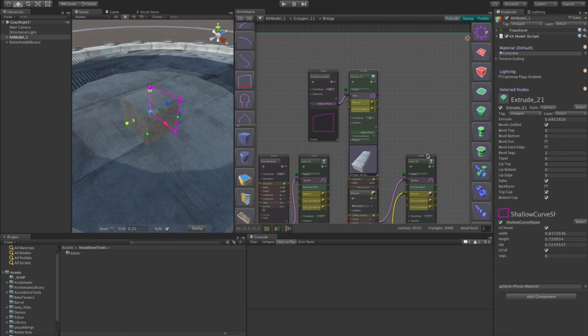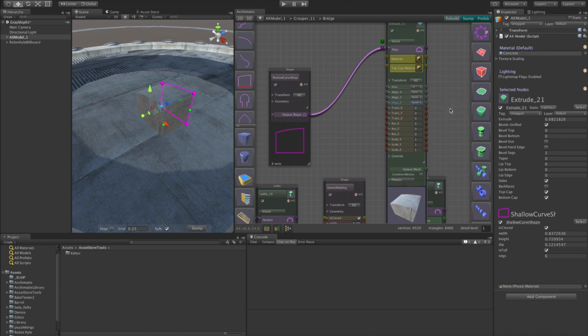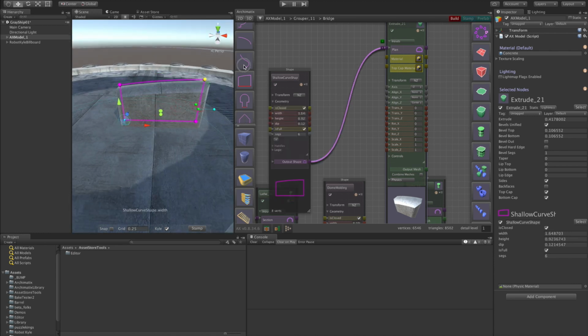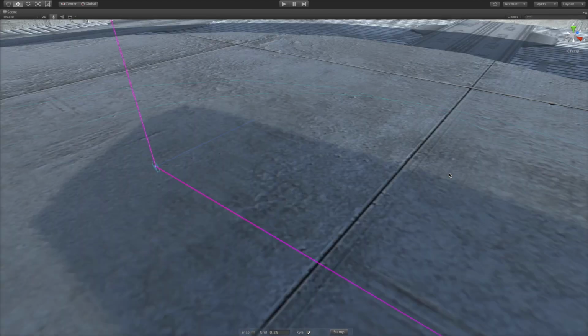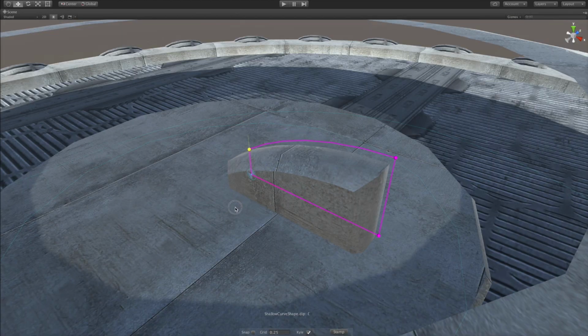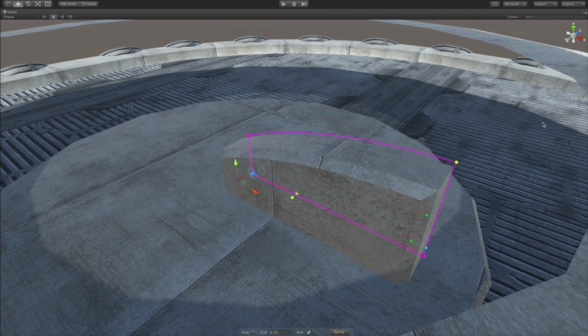It would be nice if this piece was always centered. So I will go into Transform and choose Align Z as centered. And now as we adjust the extrusion, it is always centered. I'll use that bottom green handle that we've seen before with extrude to add a bevel and adjust the shape a little bit more using its handles. And let's use that cyan handle to change it into a hard chiseled bevel.